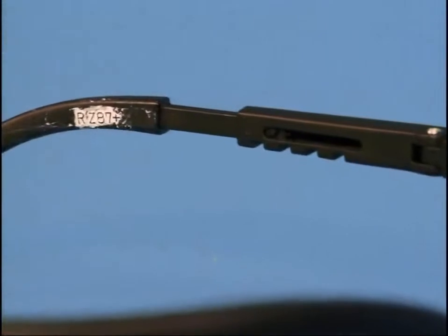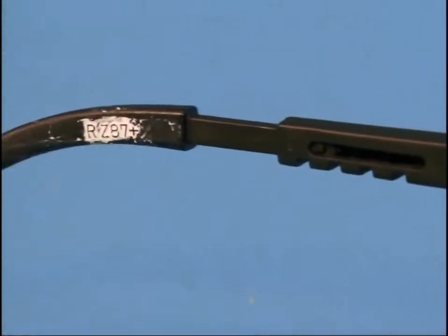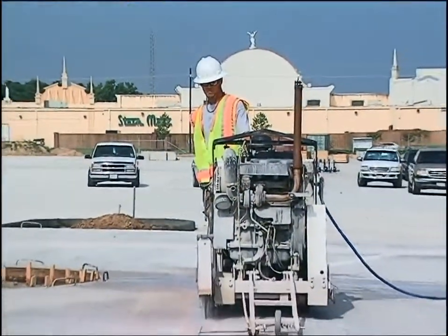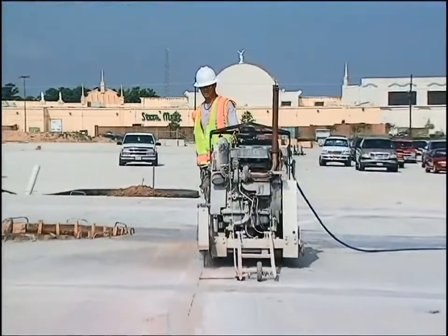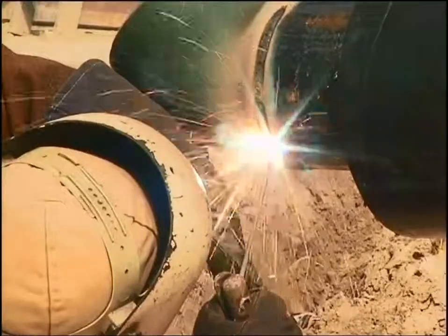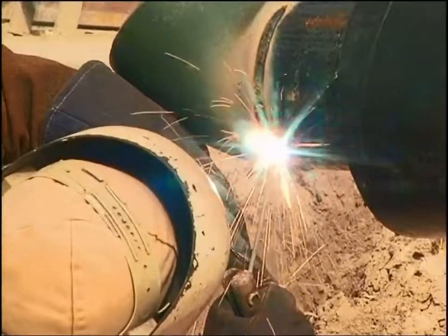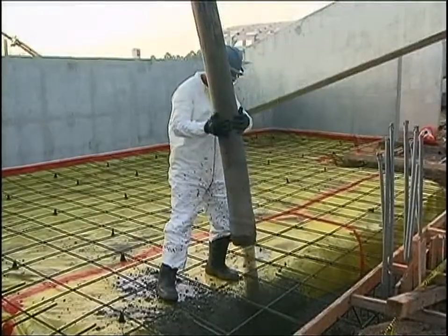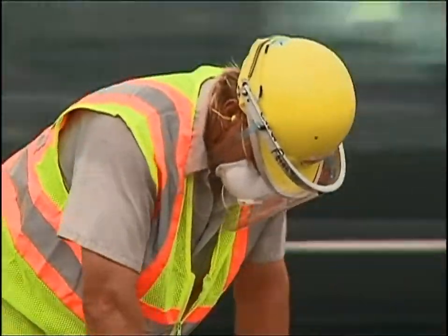You will know that your safety glasses have been rated for construction hazards if they have been stamped with the Z87.1 designation. In general, wear safety glasses or face shields anytime there is a risk of foreign objects or substances getting into the eye, such as during welding, cutting, grinding, nailing, or when working with concrete and/or harmful chemicals, or when exposed to flying particles.